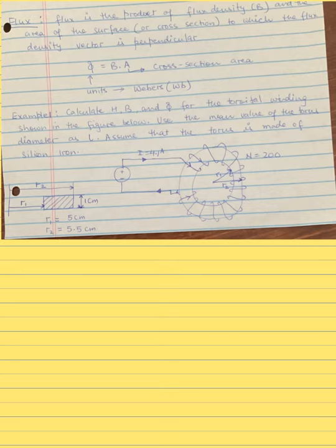So what we need to do in this case is calculate H, B, and phi. Let's look at the steps we will follow. Let's see how to calculate H. H is given by, in this case, and it's the same exercise we did to develop the expression using Ampere's law, Ni divided by 2 pi r, with r at the mean length or mean radius. Is N known to us? Yes, N is 200. Is current I known to us? Yes, it is 4.1 amperes.